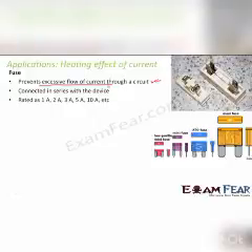So a fuse is connected in series with a device, because if you connect two things in series, the same amount of current will flow through each of them. So let us suppose some excessive amount of current I is about to flow through the device, the same current will have to pass through the fuse first.